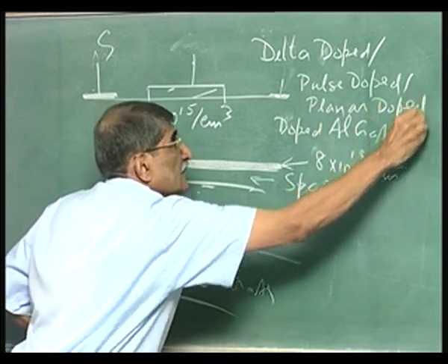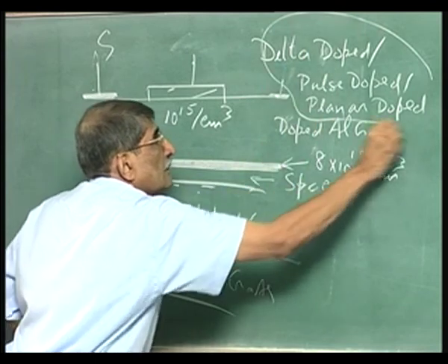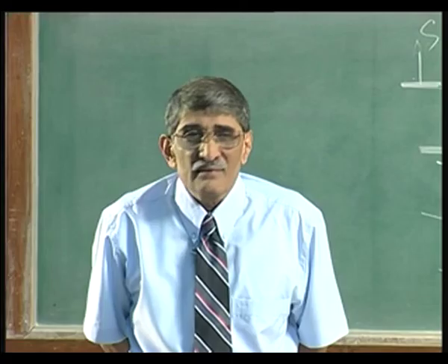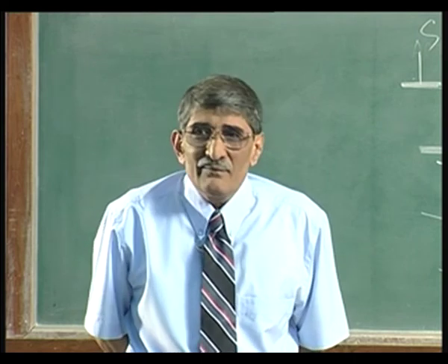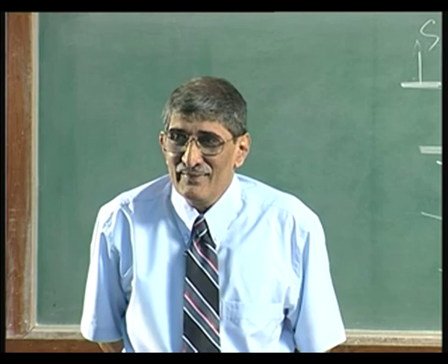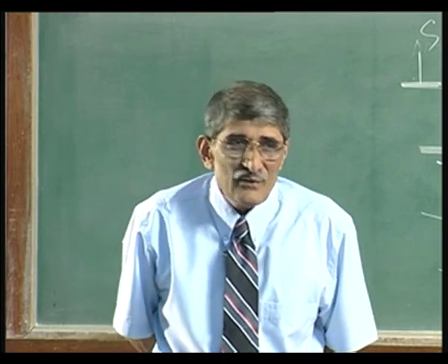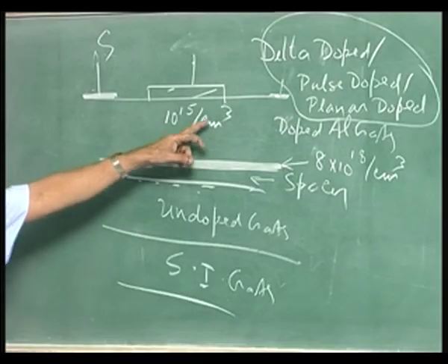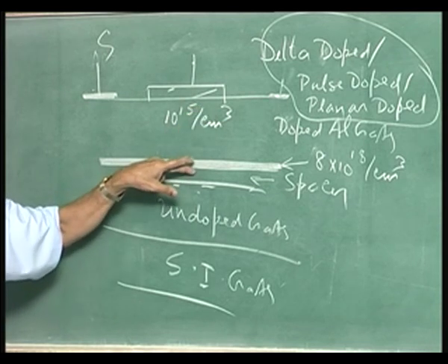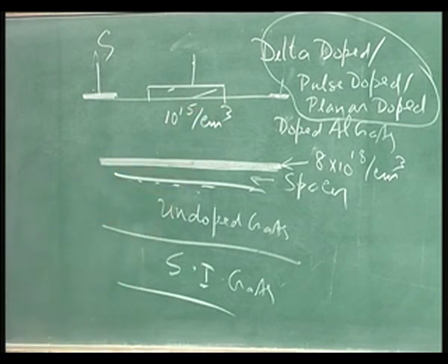Any one of the names, okay. So, if you hear the delta doped HEMT, do not get worried. It is the same drink in a different cup. Same old wine in a new bottle. Only difference is you have put heavy doping here close to that, just 3 angstroms.